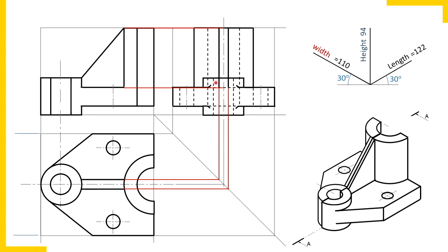The portion of the plate, that thin strip, which is overlapped, I am making hidden. Check it. I have seen many students forget to draw this portion. So this is how the trapezoidal plate is also completed in all the three views. In short, we have completed the side view and top view, and the sectional front view.